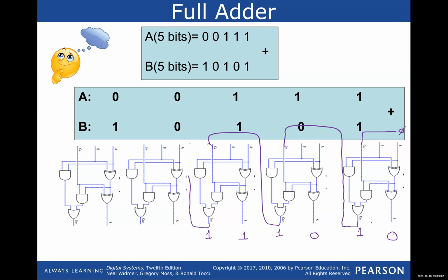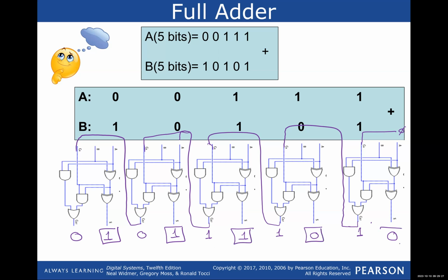You take this to the next position here. Oh, sorry, here to the carry input. So you're going to have 1 plus 0 plus 0. Summation is 1. Carry output is a 0. You carry that 0 here. You have 0 plus 1 plus 0. It's just going to give you a 1. Carry output is 0. So now where's your number? These are the summation. That is creating your number, which is 0, 0, 1, 1, 1.